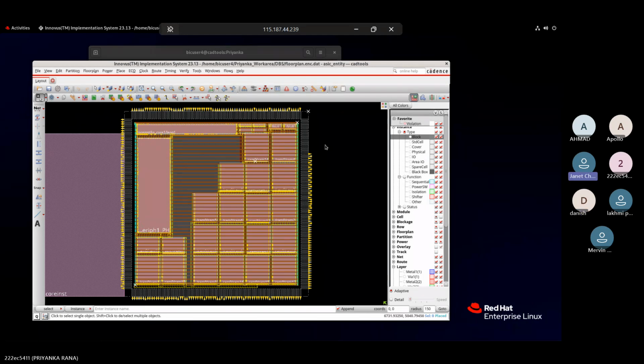For example, on a macro, if there are more macro pins on the top side, that side we will select, and we will create a ring on top and bottom. So it is like you are creating a ring especially for this particular macro alone. Now in this peripheral macro, on the left and right, we have created the VDD VSS ring, because there are more macro pins on these sides of the macro.